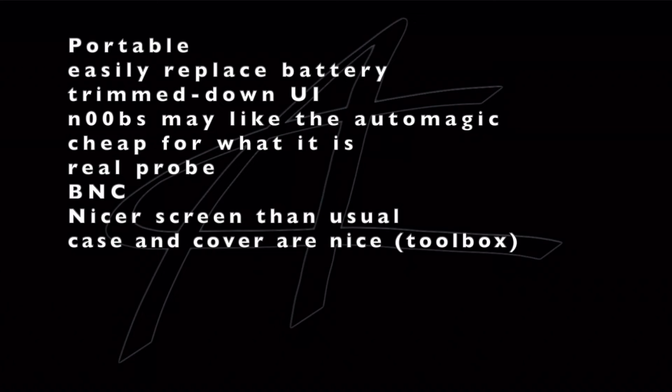Another positive is that you can use real probes with it, which is nice. You're not relegated to built-in alligator clips like some of these. And it has a built-in BNC connector, so that's nice. You don't have to use adapters or anything like that, and it's nice and rigidly attached to the device and the board.